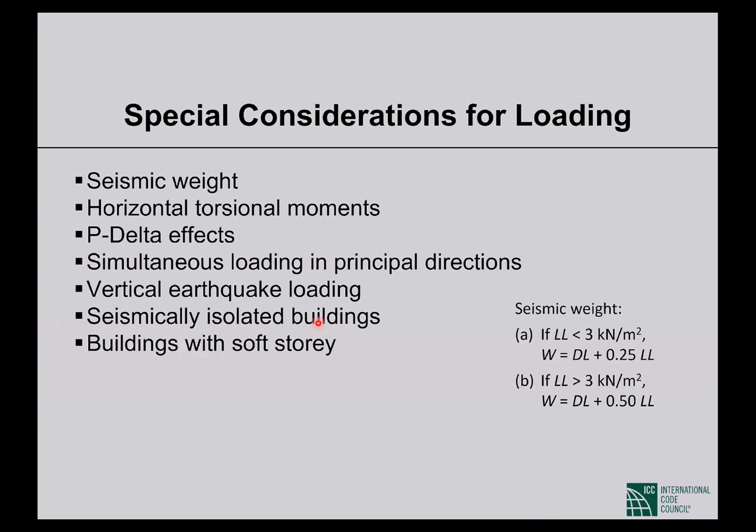And for buildings with a soft story, there is a special shortcut. If you determine that there is a soft story, but you don't want to make a detailed dynamic analysis, there is a shortcut. Actually, this is taken from the Indian Building Code: only for soft story, you can use the equivalent static loading, but you have to magnify the moments in the soft story, usually the ground floor.